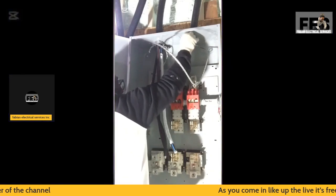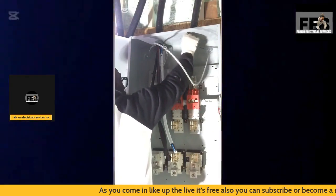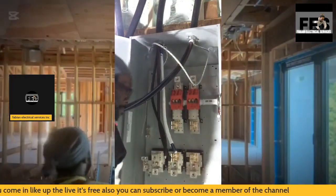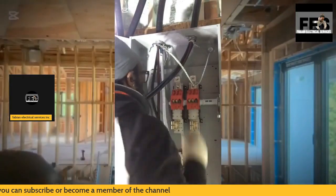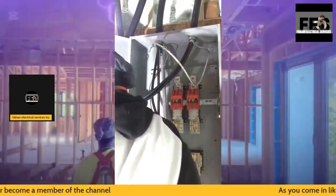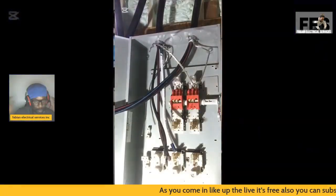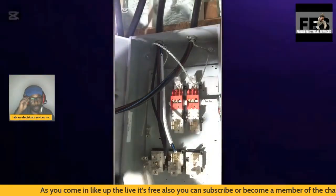It's always best to have your line and loads coming in to be separated. Never have them touching each other. It is a code compliance rule that states that your feed that's coming in, your main feed, is not supposed to come in contact with your actual load side that's going out. So for this reason, you're going to see the installation.